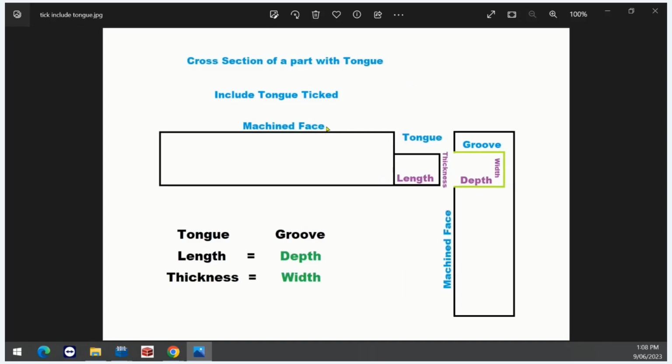Conversely, when it's ticked, it will machine the tongue to be a separate thickness to the material of your carcass. Obviously, everything works off the machined face, so you can't have screw holes in this side with the tongue machining from this side. It would have to drill the screw holes right through, or the shelf holes.